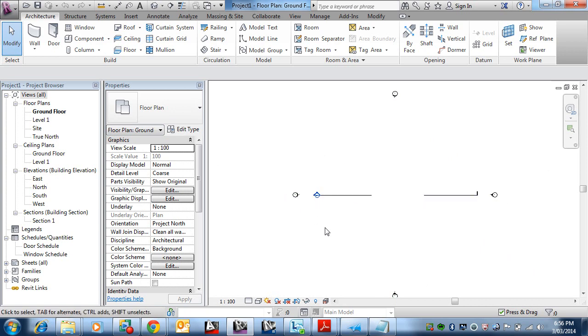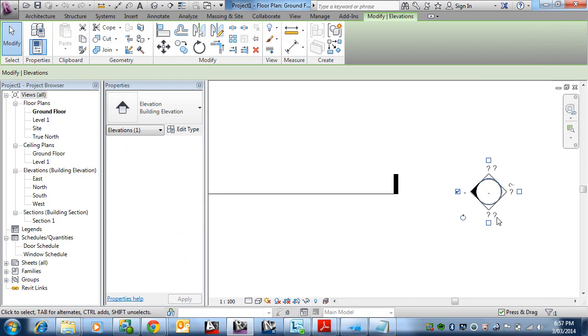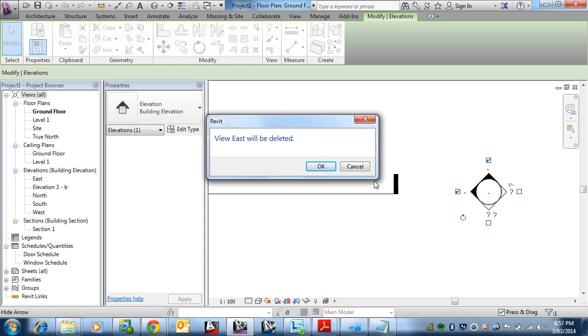What you aim to do is draw your project in here somewhere, and then it'll appear in the right spot. For example, your elevations will come up right, and your sections will come up right. It's not to say you can't add more elevations. You can add more, say, 45 degrees if you like. You can rotate these as well. You can click them and turn on different parts of them. For example, I'll make that look that way as well. I'll turn off that one. Oops, I won't do that. Cancel. Otherwise, it'll delete the view.